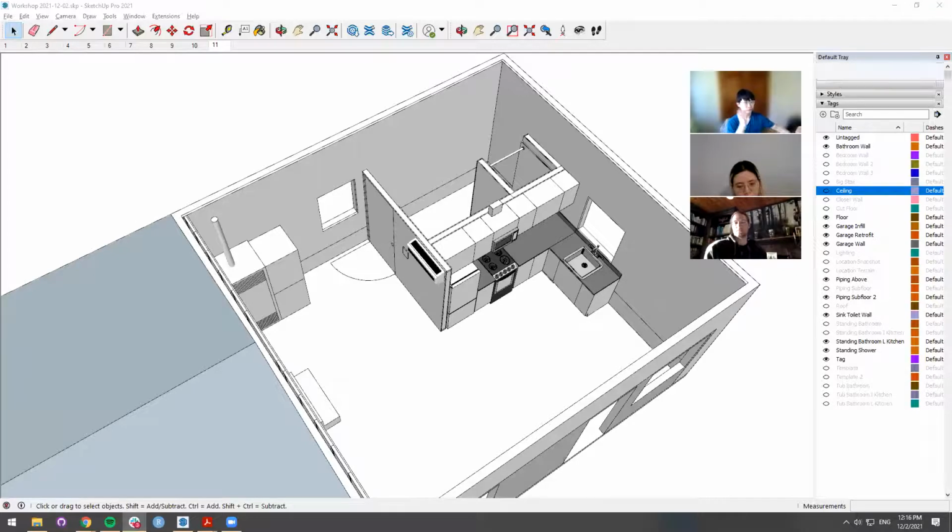And once you start figuring in the slope necessary for the subfloor plumbing, you might run into a height issue with the floor. You might have to fur it up 6 or 7 inches by the time you get to your finished floor. So that might also make that option unrealistic in at least some situations. So I kind of agree with likely leaving the floor itself alone and building everything else around it.